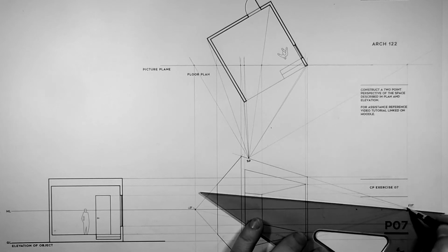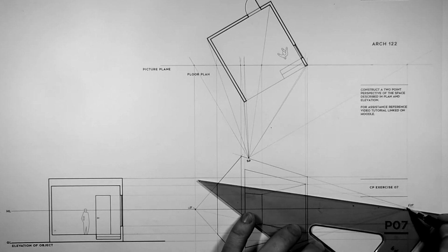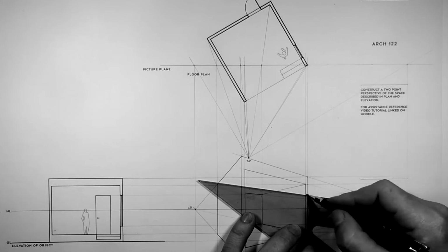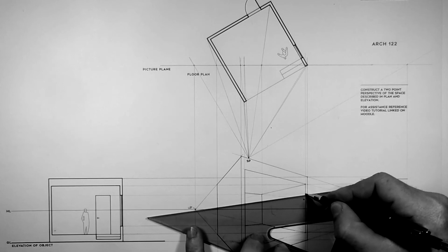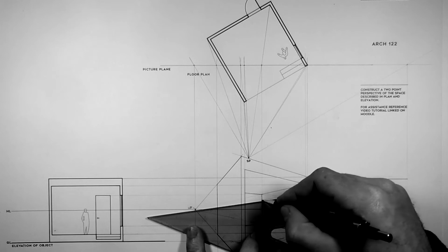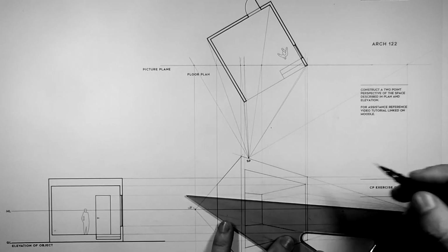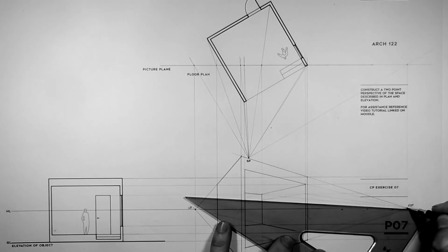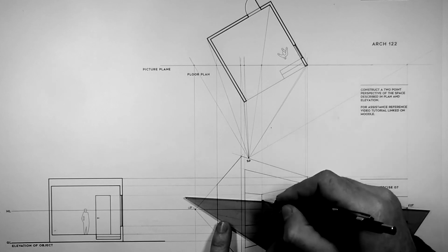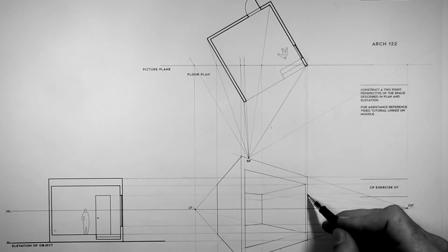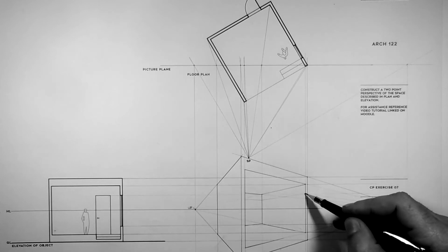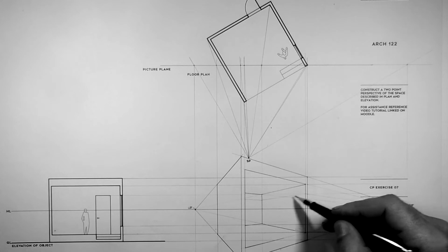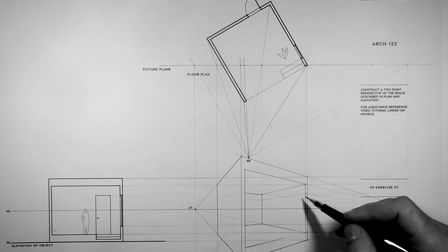So from the right-hand vanishing point, we pass through that location, and then we stop there. And then we use that intersection to turn back towards the left vanishing point. We come back to the back of this wall, and then from there we switch back to the right-hand vanishing point. And so that height of 8 feet above the finished floor has been projected from there across that little thickness of the wall, back to the back of the room, and then across.